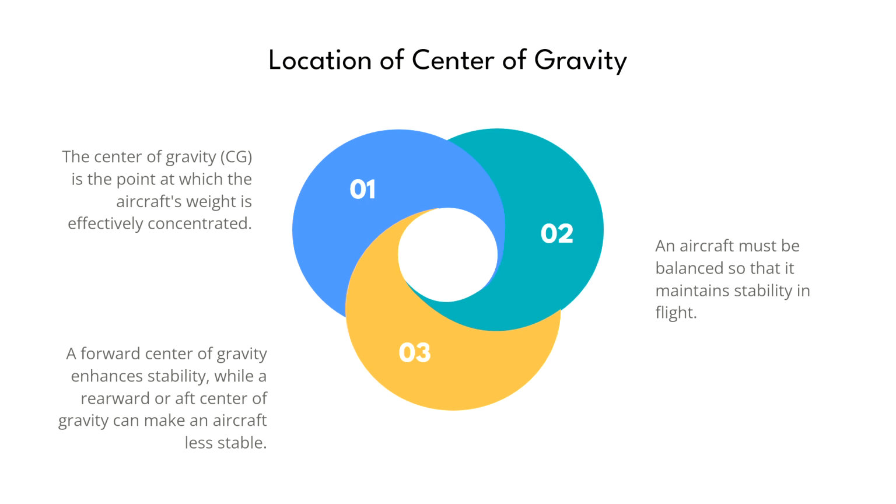So when you have a forward center of gravity, you have a stable feeling, but nose heavy. Longer takeoff distance, increased induced drag, and higher stall speeds.